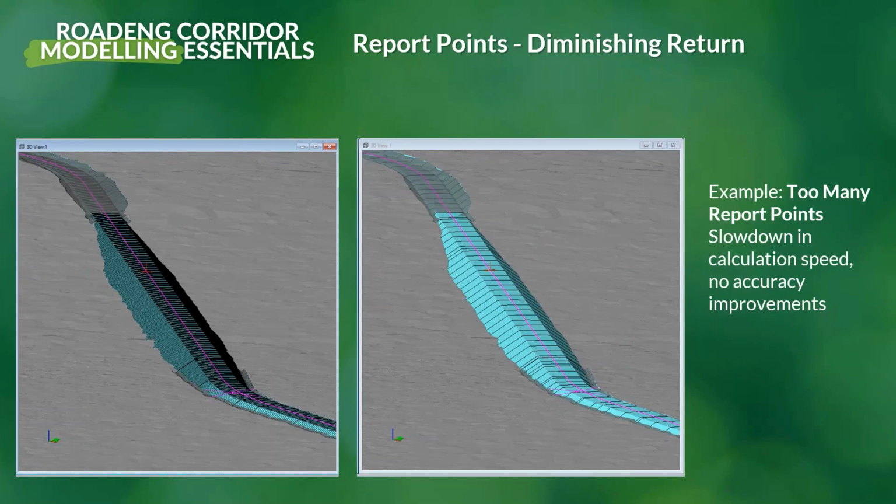So this is that second key concept: yes, you can add too many, because you're going to start to have a significant impact on your computer's performance, especially for our clients who are working on those extremely long road projects, the ones that are in the 20, 30, 40 kilometer range. Yes, report points do play a very significant role.